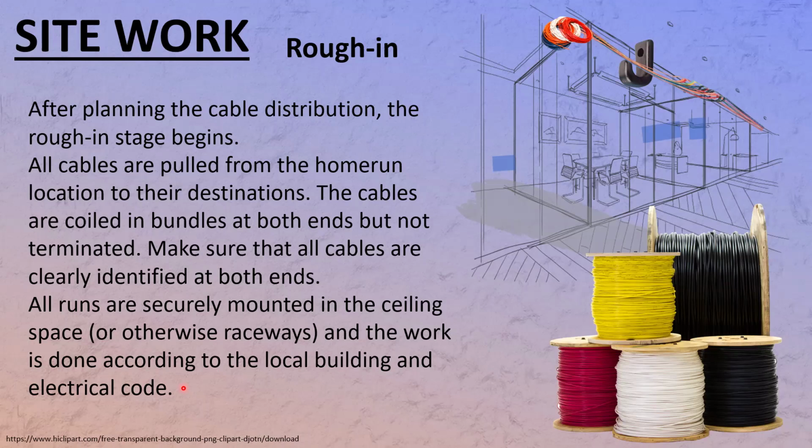The cable specifications for FT4 and FT6 are no different. It's just the type of jacketing that is used. One of them burns easily, which is FT4, which is not fire rated, and FT6 doesn't burn as easily, it's fire rated. And I already talked to you about that last time we saw each other. Right?